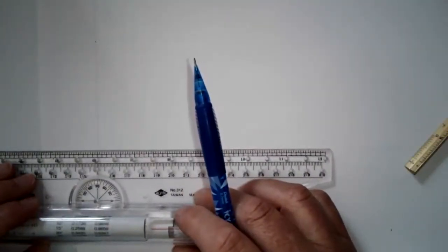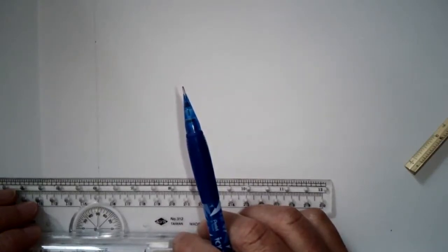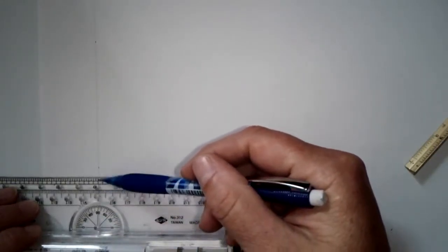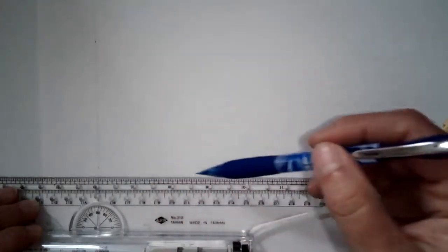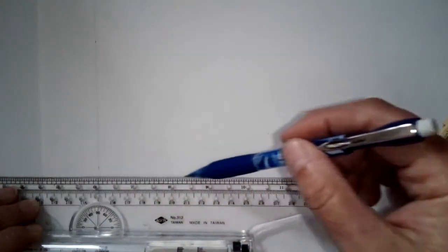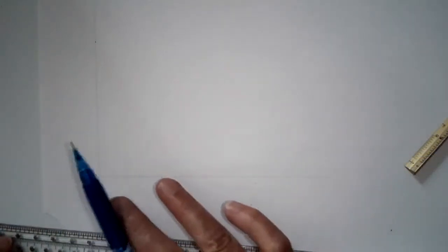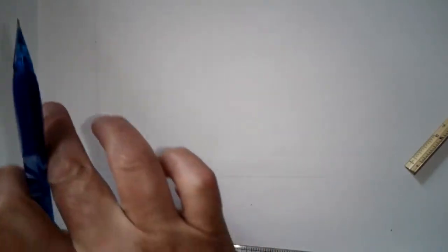So I've got it lined up like this, and I want to see that the line is lined up with 90 degrees all the way through. And then I know that this line I'm going to draw as a construction line, as the start point for my horizontal line work, is going to be perpendicular to the original line. So we keep going back to that original line. It's going to ensure that your stuff ends up being a lot more parallel and perpendicular if we do that.